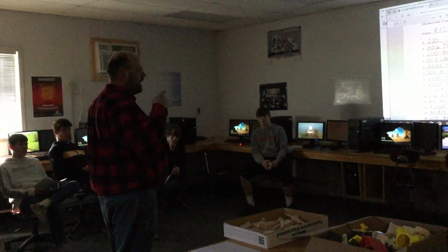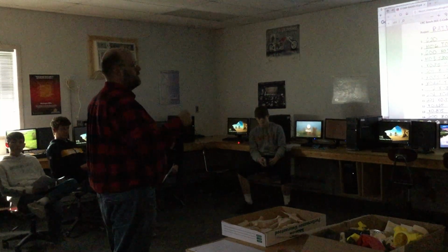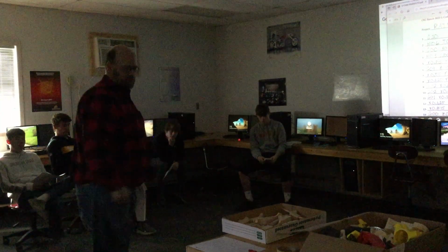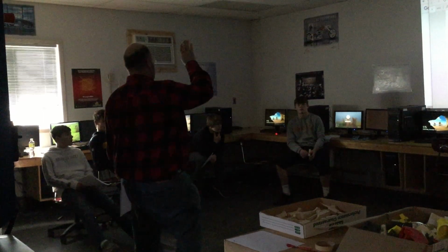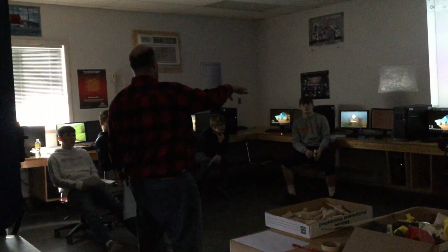So you've got to have that in your mind when you're setting this: decide what kind of material you cut into. If we get a chance to get some more wax or plastics, then we can even speed the feed rate up faster, because these are a lot softer. So you can cut them a lot smoother, a lot faster, a lot quicker through the process. But all you have to do is go back and change your feed rate. You can change your feed rate at any moment through this.